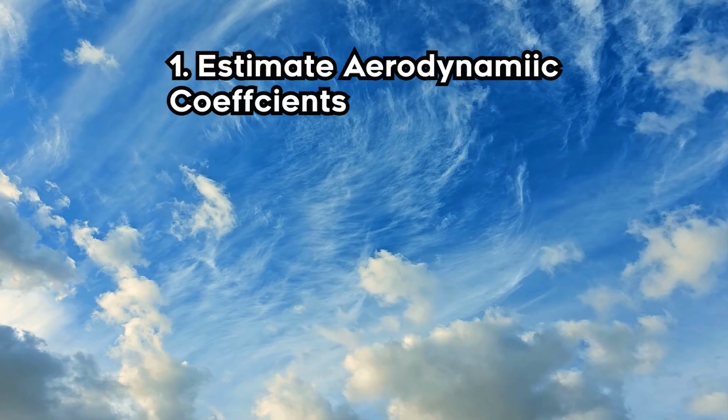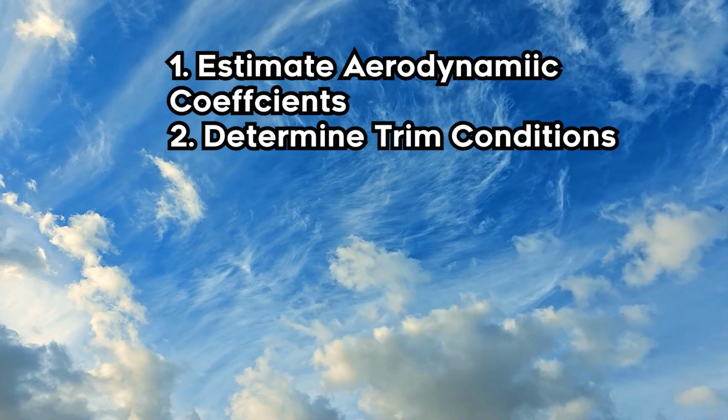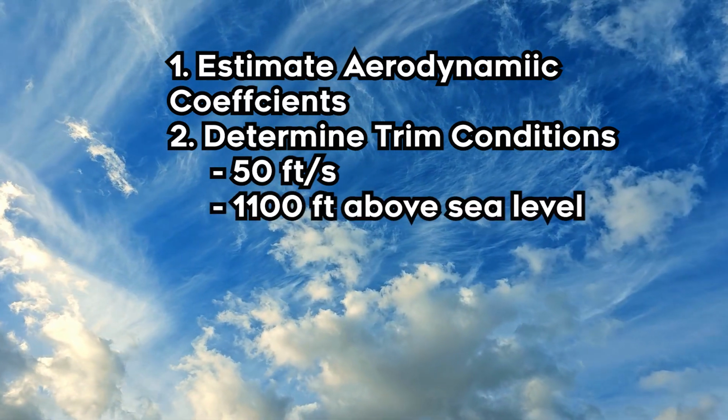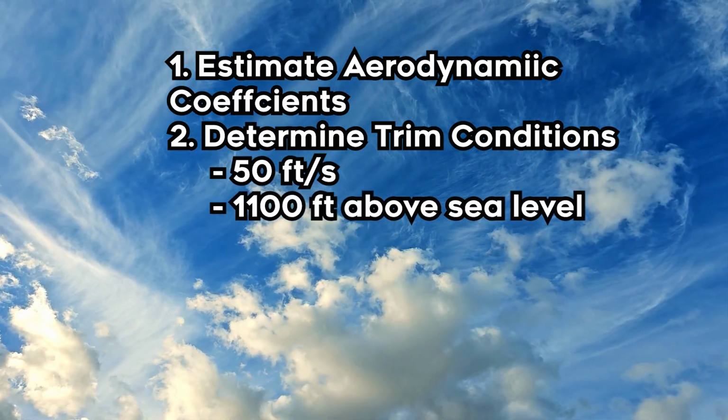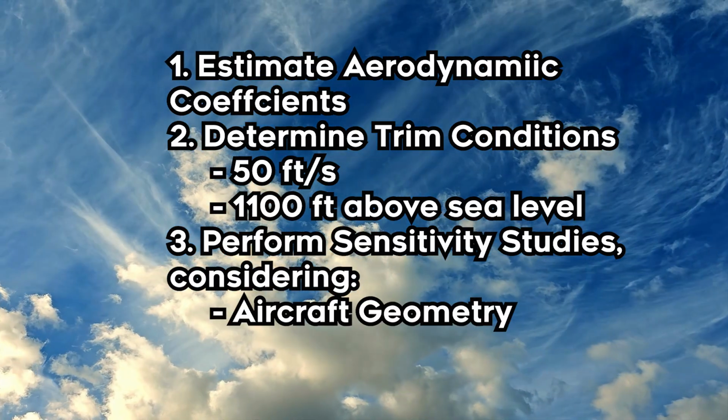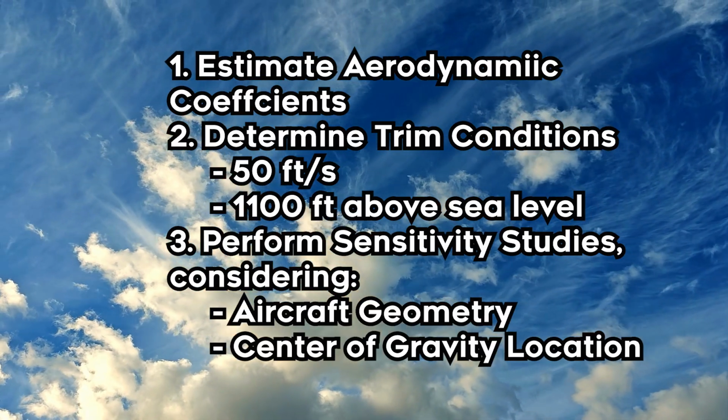We used advanced aircraft analysis, AAA, and Athena Vortex Lattice, AVL, to estimate our aerodynamic coefficients, determine trim conditions at our case, which was 50 feet per second and 1,100 feet altitude, and perform sensitivity studies with respect to the aircraft geometry and center of gravity location.